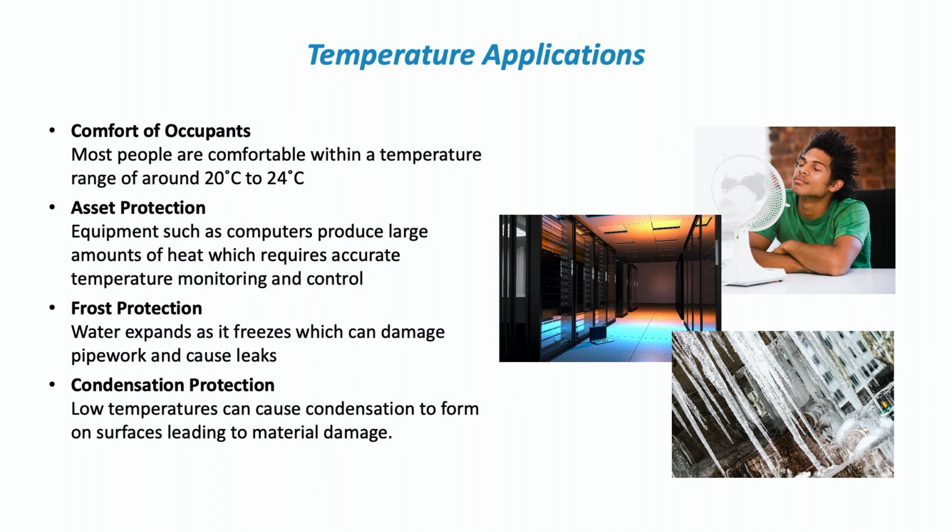Most people are comfortable within a temperature range of about 20 to 24 degrees C. Somewhere in the middle, 22 is about the spot for that. Don't get too obsessed about it. Different people feel temperature in different ways. You can't do anything about personal preference, but if you keep it within those bounds, then most people will be comfortable.